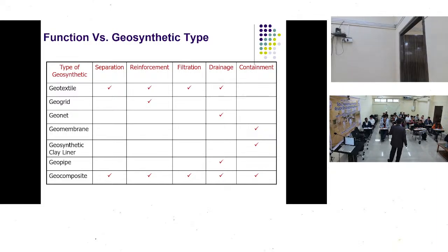Similar things nowadays, people have been forming cement blankets. In cement blankets also, they have filled in certain cementitious material. On both the up and down side, there is a normal type of geotextile. For canal lining, there is a lot of usage. So you are just laying out the blanket and just watering it. Whatever shape it takes, it takes that shape because of its flexible nature. And as soon as you water it, the cement gets set, and you get a very hard surface, which is highly erosion resistant. And even when the upper layer of the geotextile gets removed or abraded, still that mattress functions very fine.